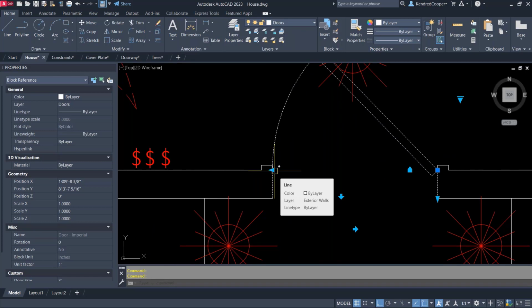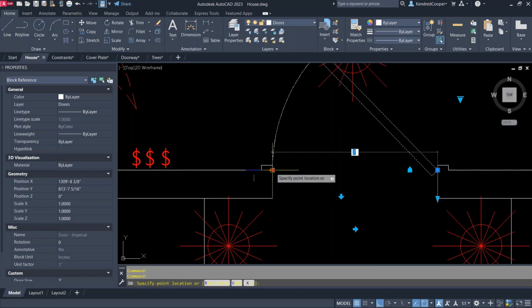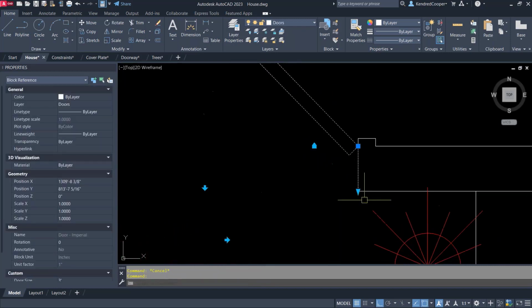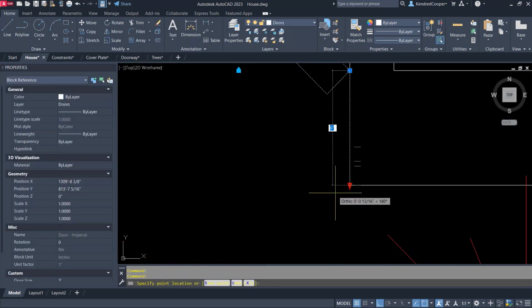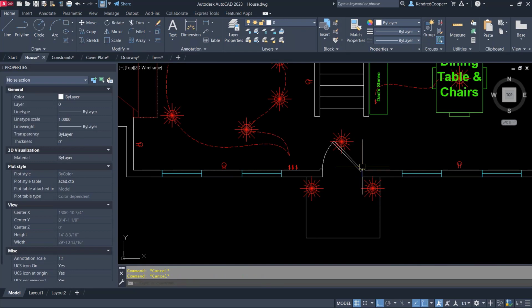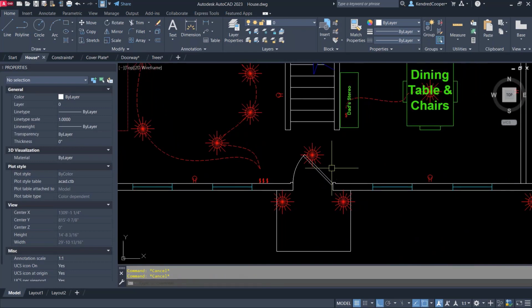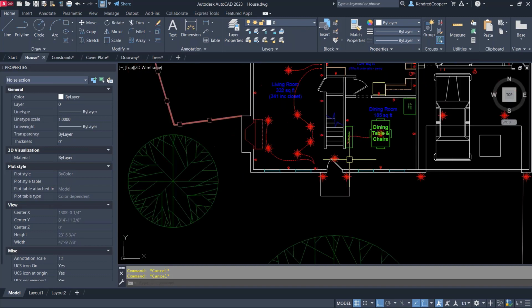Additionally, how wide is the door? This grip over here allows me to resize it from say 3 feet to a 3'4" door. Size it down to 2'8", 2'6", get the idea. Not only that, but you also have the option of the wall thickness, a 6-inch wall versus a 5-inch versus a 4 3/4 versus a 4-inch. This is all information built into the symbol, part of that block authoring environment.